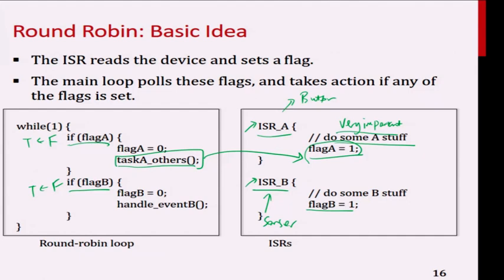So if there is an interrupt because there's serial port data coming in, or interrupt because somebody pressed a button, what am I supposed to do? What is the most important thing that I need to do to prevent loss of data, loss of information? So let me do that important activity first inside the interrupt service routine, and the other things I can do later in a function.